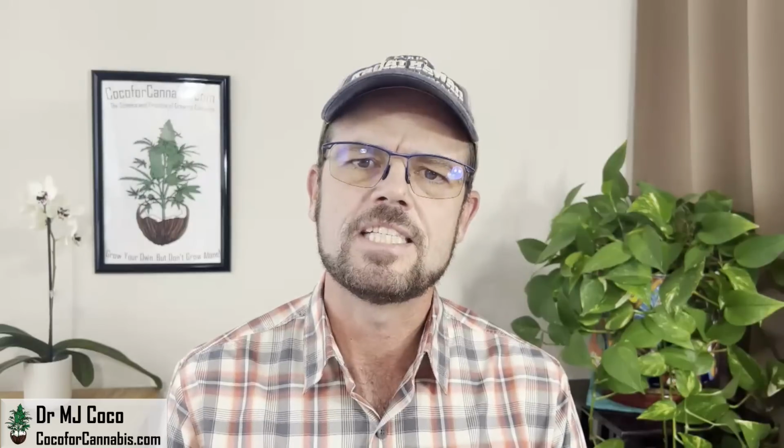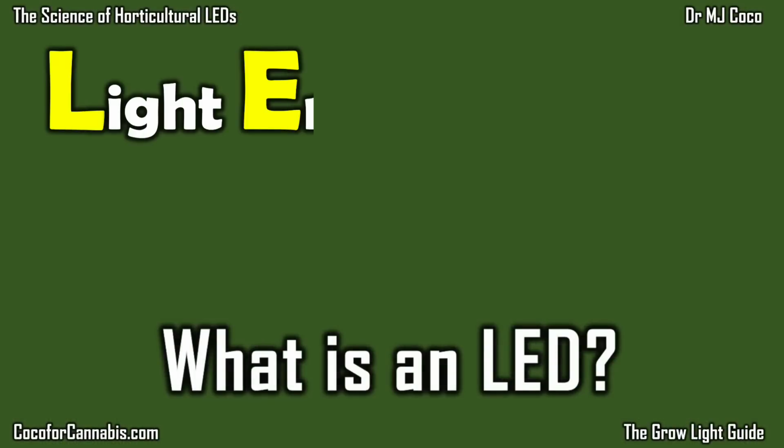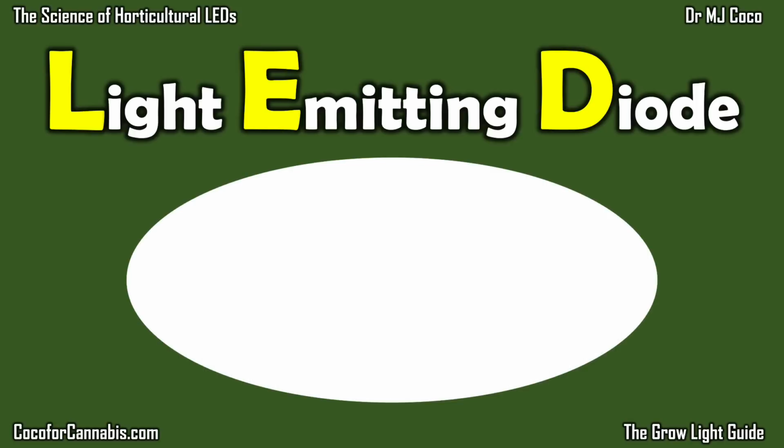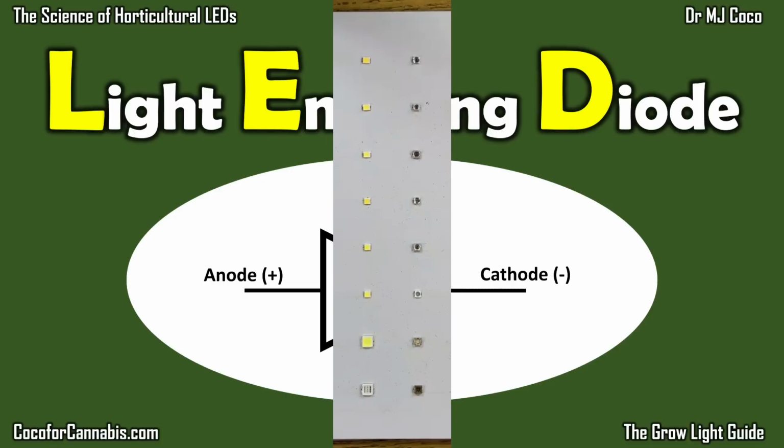I'll start with the most basic question. What is an LED? LED stands for light-emitting diode. A diode is a simple semiconductor device. Diodes have a positive end, the anode, and a negative end, the cathode. This is the symbol for a diode. For an LED, we add two arrows here that represent light. When current is driven from the anode to the cathode in an LED, light is produced in a process called electroluminescence. More on that in a minute.